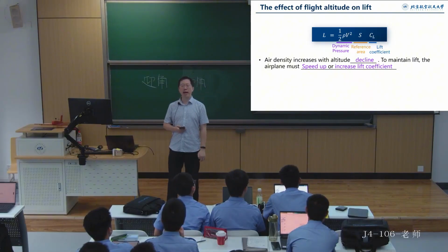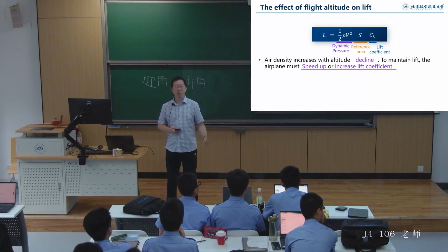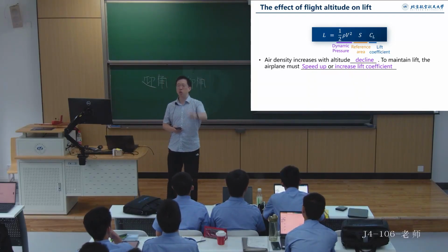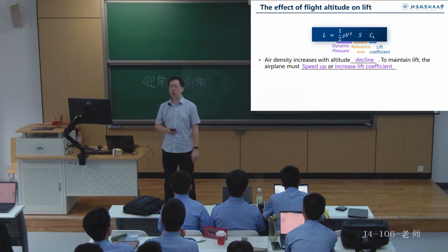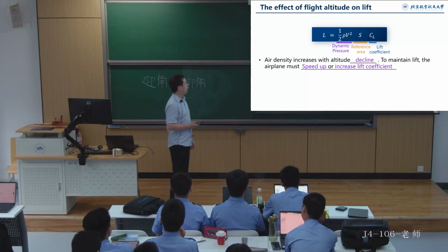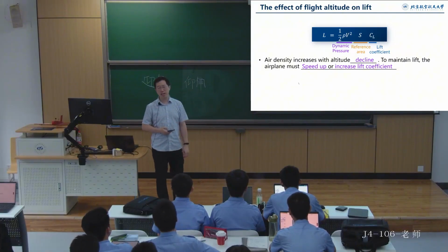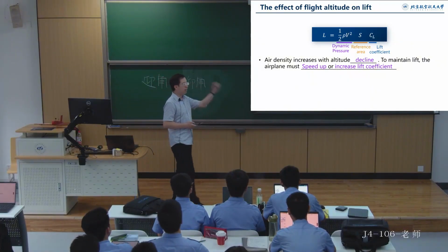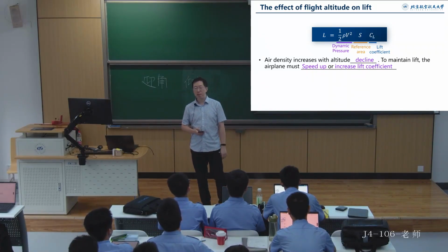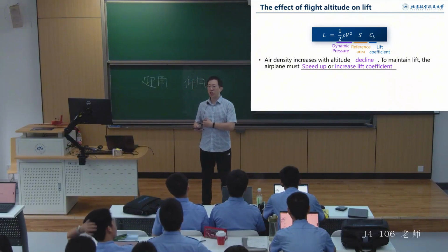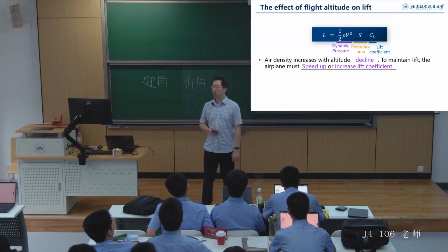What kind of airspeed is this? When we do a physical analysis in this lift formula, what kind of airspeed are we using? It's true airspeed, right? Yes, that's correct. Now, let's consider the situation. During actual flight, when we fly general aviation aircraft, do we have instruments that display true airspeed? No, right? So what kind of airspeed is displayed by our aircraft at this time? It's indicated airspeed.